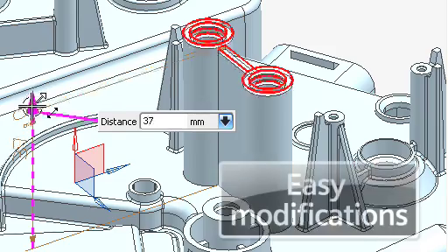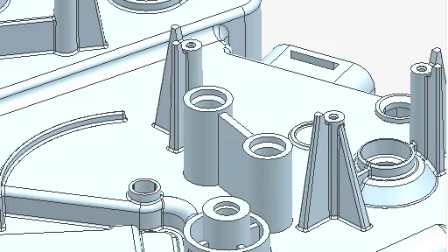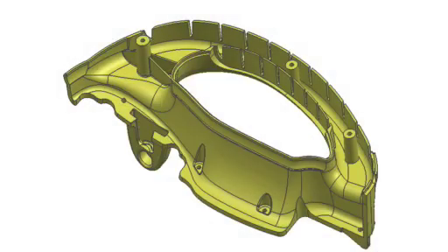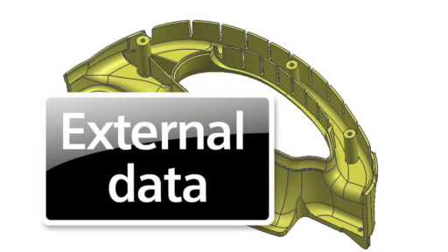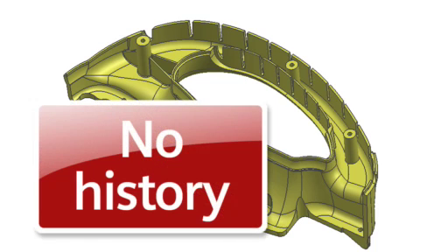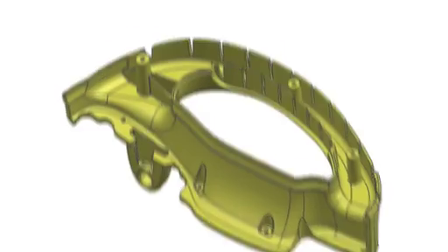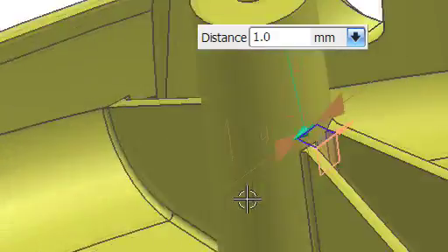In this case, synchronous technology enables you to use powerful engineering tools for simulation-driven design optimization regardless of the origin of the data. Consider this plastic handle. With a design delivered from an external supplier, our in-house team has been tasked with considering some alternatives to increase its strength. The problem is that the supplied model doesn't have any feature history. With traditional approaches, we would be forced to make manual changes to the geometry or to rebuild the ribs with parameters and then remeshing and reanalyzing at each step.